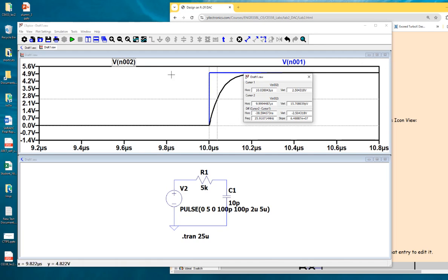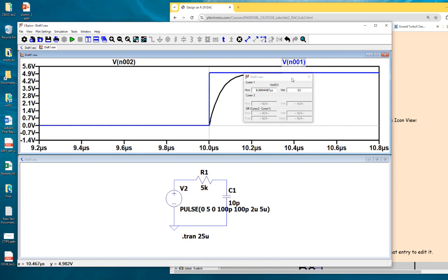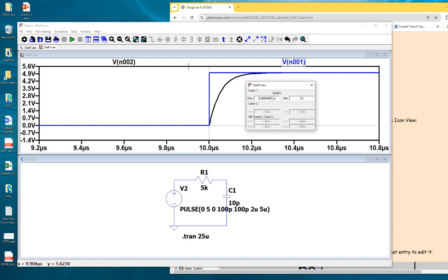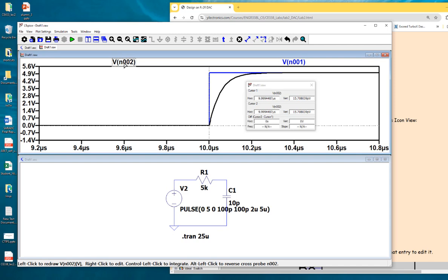Okay, just one more time. You double click it to bring up the two cursors? Yeah, you click it twice on one signal line. So there's no way that I click this one to bring up one cursor, then click this one more time to bring up another cursor. No, it's not going to work. A single click will only bring up one cursor. If you want to bring up two cursors, it has to be pointing at the same signal line. Double click, two cursors.